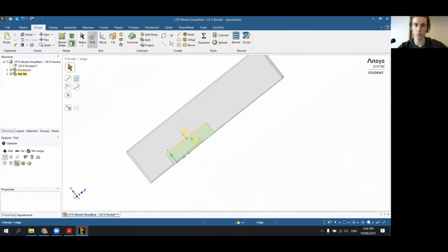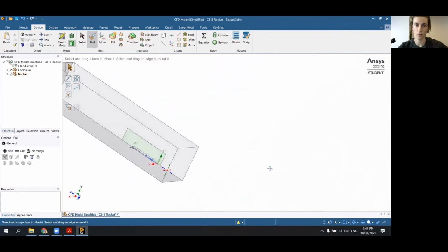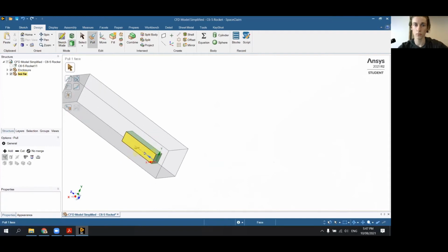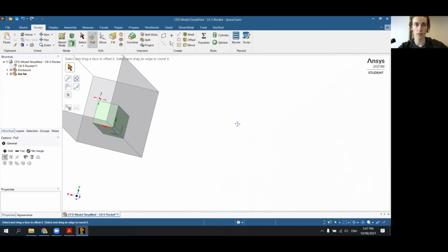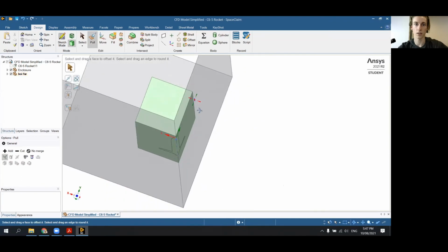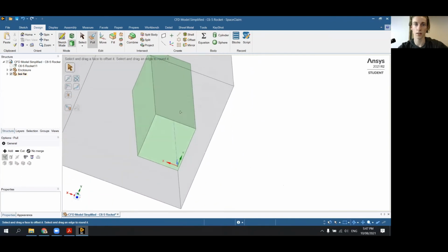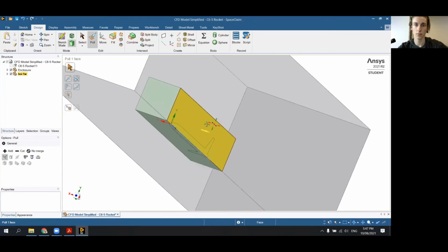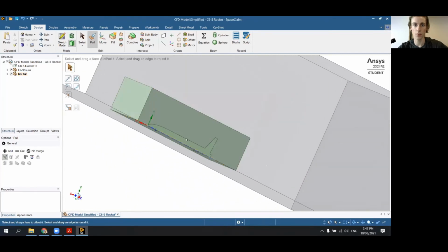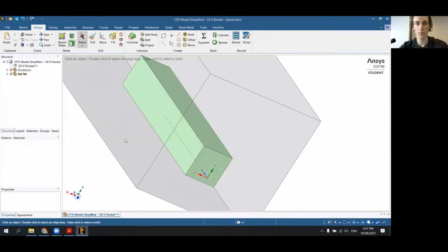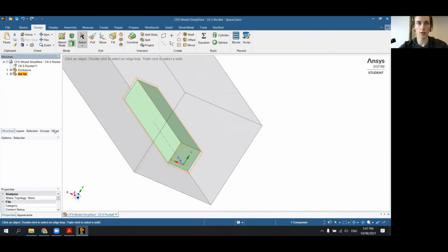Just finish that sketch. And then you can see we have the extrude tool now in the design tab, or the pull tool. And we can just pull that. Again, you don't have to worry too much about exact measurements, but it's a region around that rocket. If you want to change the size of that, just drag it in a bit. Maybe you want to go a little bit further from the nose. Yep, I'm pretty happy with that. Just press escape. And that's our component now.